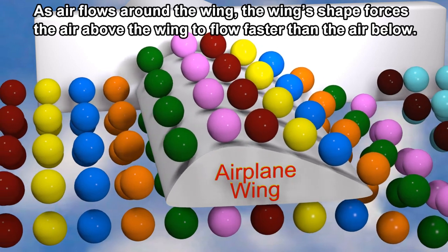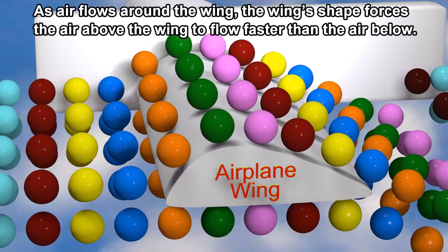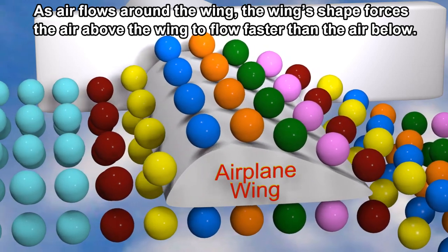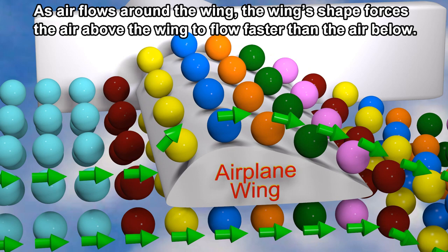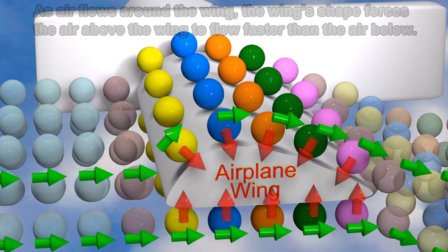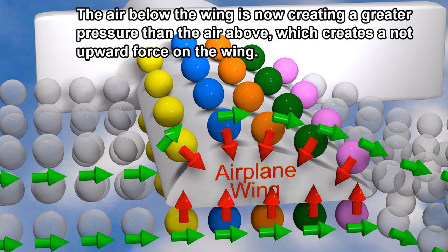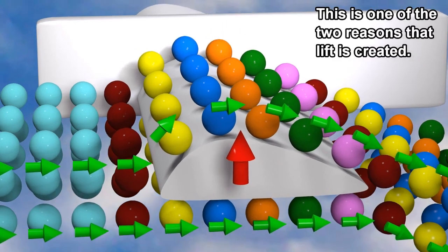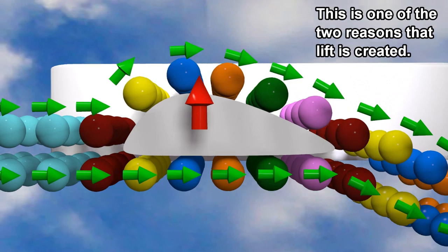As air flows around, the wing's shape forces the air above the wing to flow faster than the air below. The air below the wing is now creating a greater pressure than the air above, which creates a net upward force on the wing. This is one of the two reasons that lift is created.